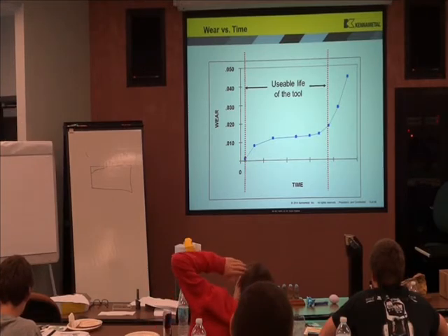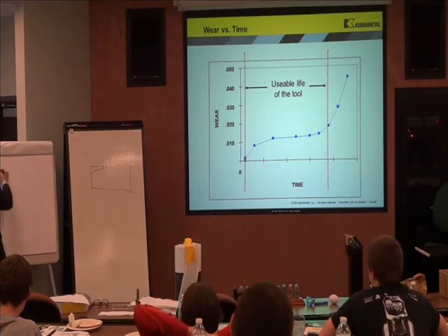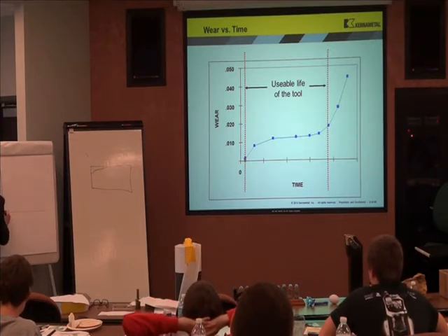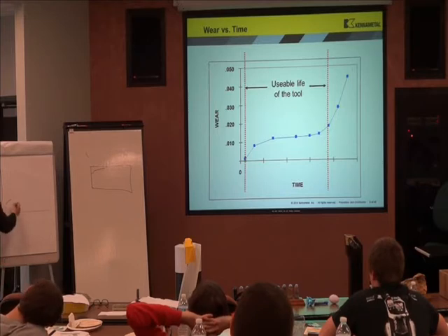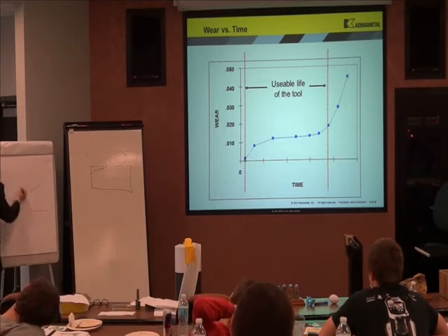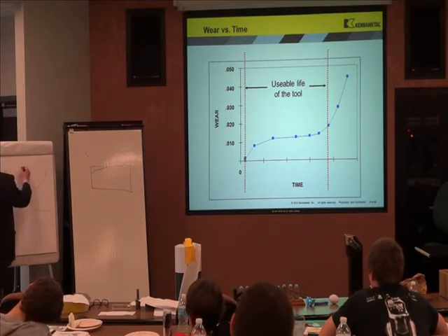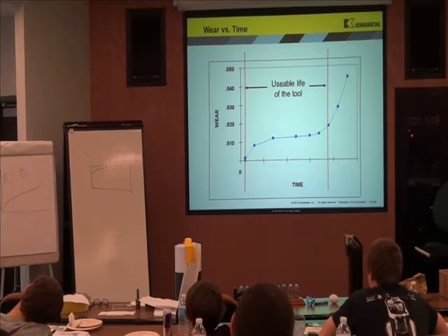And what I mean by that, usually I get that rapid break-in, and it's a little bit more of an angle, and then it goes here. That one over there is a little bit flatter. So this is my A zone, this is my B zone, and this I call my oh no zone. Because once I get out there, I don't know what's going to happen. This area here, this is the break-in zone, and what I call this is the constant wear zone.